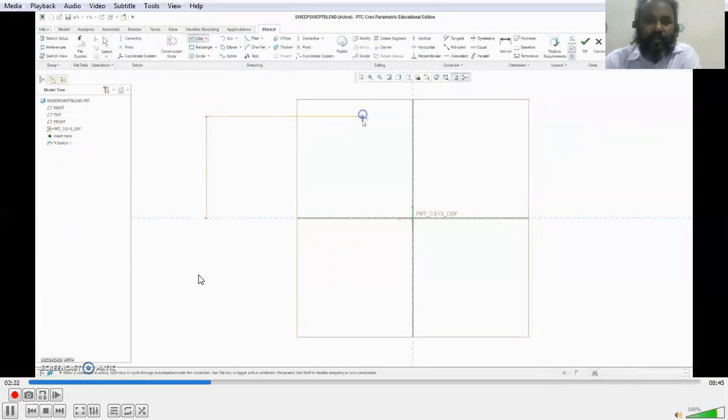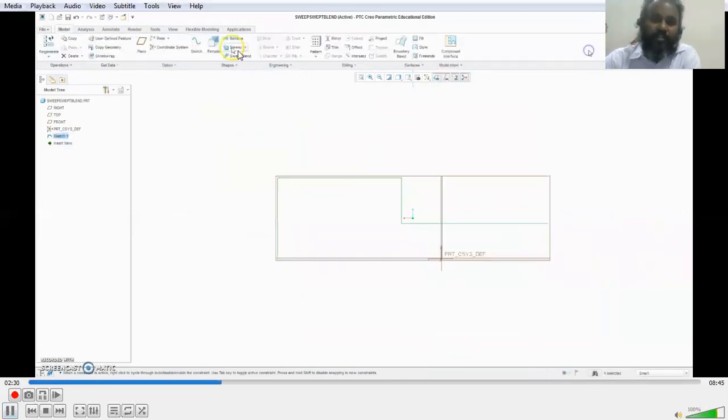So what I'm trying to do is I'm creating a sketch and using some straight lines, a combination of straight lines, and I'm going to add a section here at the end and sweep it through the entire given trajectory or the pathway. So once the sketch is done, press the tick button and move to the sweep options chosen. Like the last time, I'm going to choose this, and that is going to help me create.